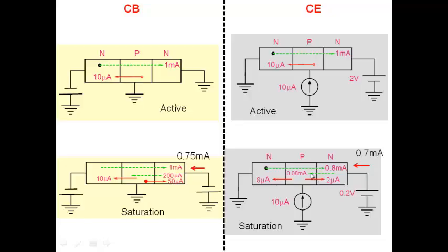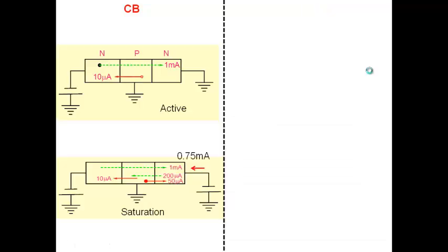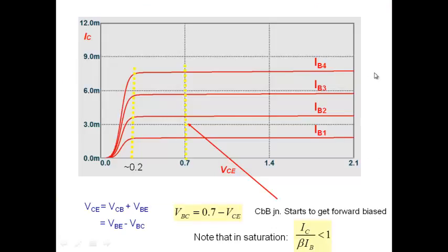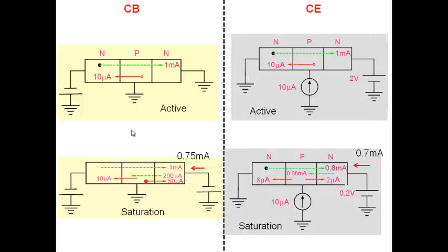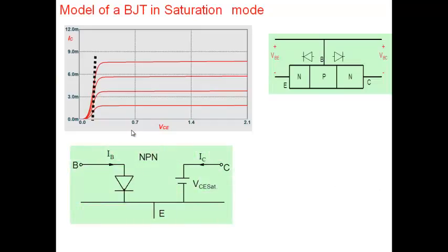And so this redistribution of base current is responsible for the falling of current. Anyway, the important point, at least from an amplification point of view, is to be aware of a transistor which looks in this particular manner here, where beyond 0.2 or so, we are in the effects of saturation setting. Okay. All right. So how do I look upon a bipolar transistor in saturation mode?